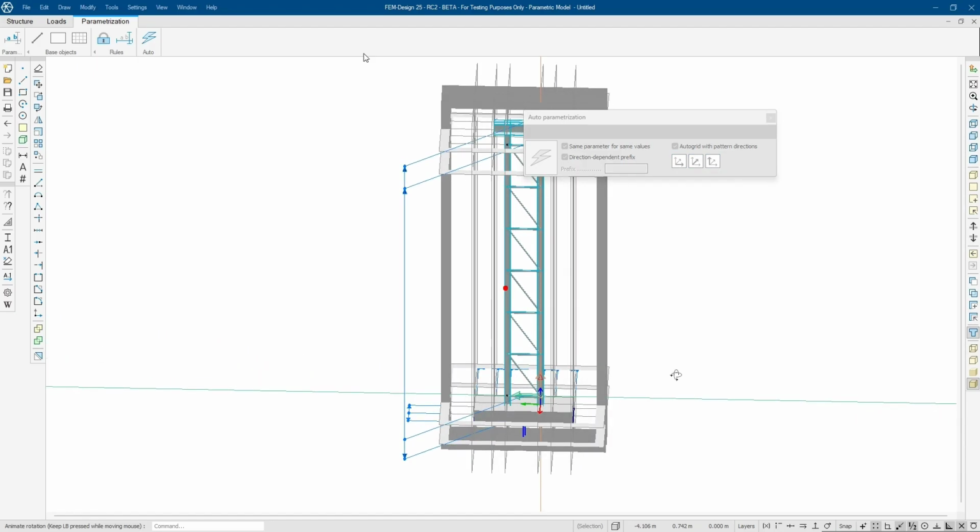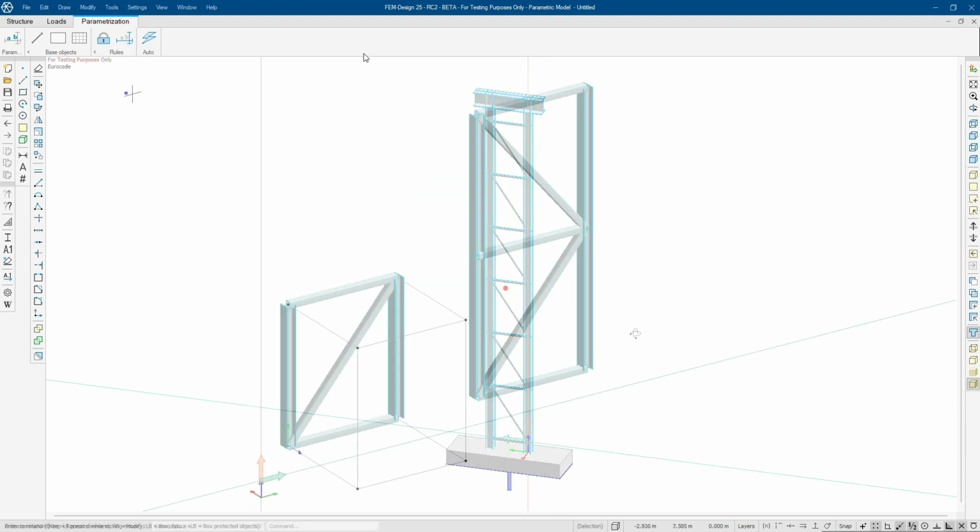Oh, there's a question: do we have an option to export bar node forces floor level wise? Yes, we have an option. We have a tool called list, and if you click list, you can choose like one level, or you can choose like selection. You can select one floor, and then you can just get those floor beams or one floor plate node transformations. Of course, maybe I'll send you the answer after this webinar. It takes like 5 minutes to show, but there is a possibility.